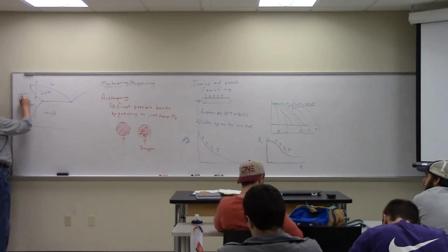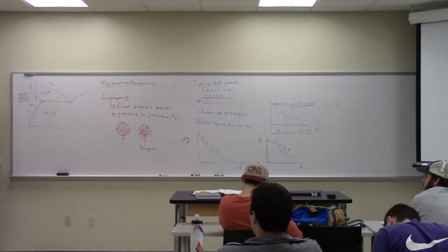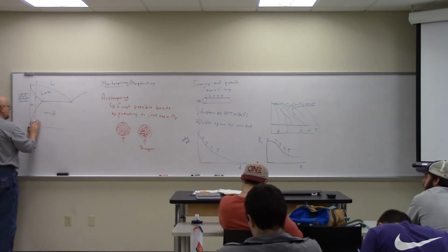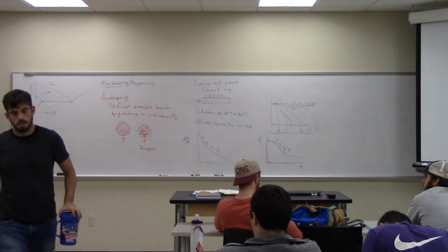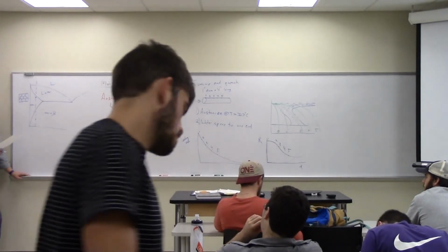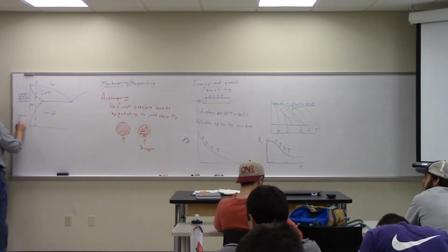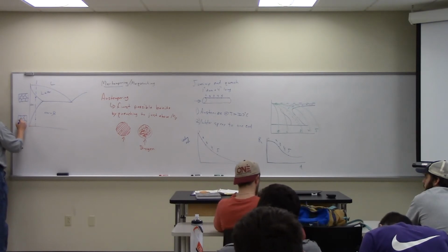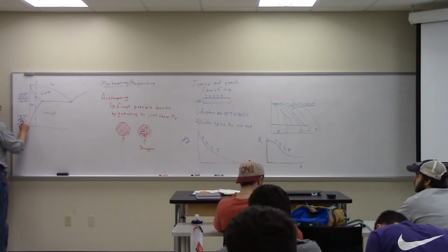Right, so at that point, I just have a bunch of grains of alpha. Okay? What do I have here? What's that look like down here? Alpha with beta and the grain boundary. Right, so here, I'm gonna get the same idea. But I'm gonna get a lot of beta forming at the grain boundaries. Right, so we get what's called grain boundary decoration.